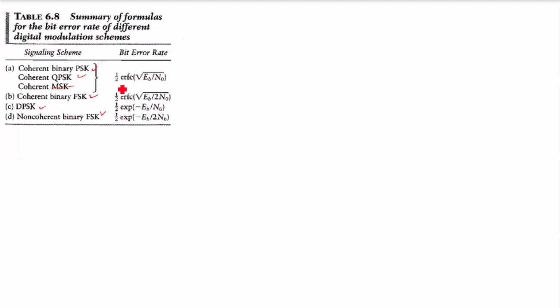Okay, now you can see the probability of error, bit error rate. Probability of error in the case of coherent binary PSK, QPSK, coherent MSK, it is about half erfc of square root of Eb by N naught, isn't it? Yes or no? Or if you have any other value, coherent BPSK. What about the probability of error in coherent QPSK? Yuvraj? Sir, it is the same only. Is it the same, or is the half not there? Yeah, it's double. Sorry, it is double.